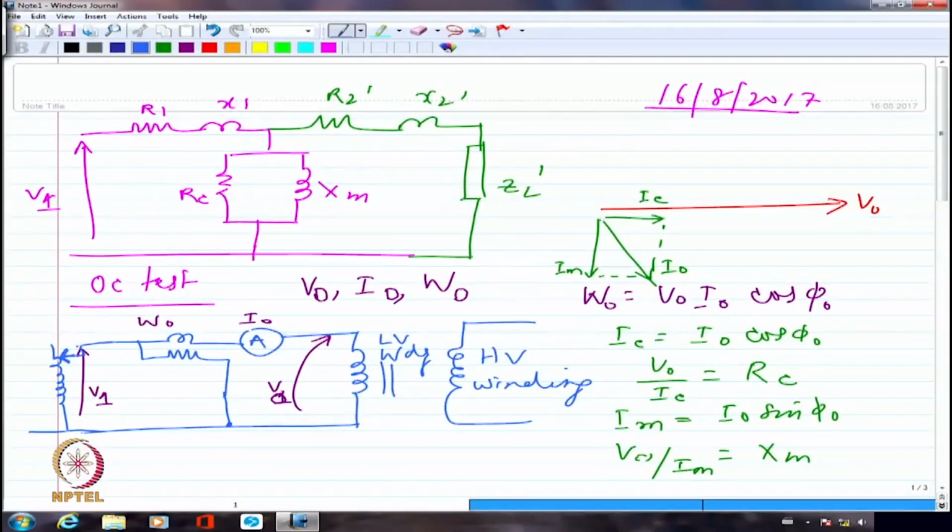Open circuit test does not require an isolation. But if I am plotting a BH loop, because I am connecting the power components directly to the CRO, and CRO is meant only for electronic components, not meant for power components, I am mingling the two. I better take precautions. I'm saying that in the short circuit test, can't we use isolation transformer for managing the current here?